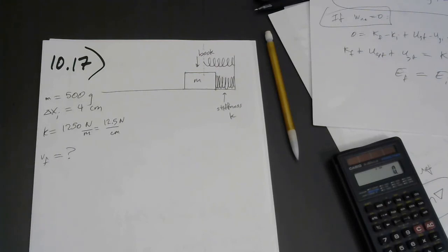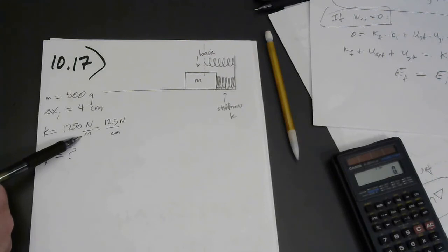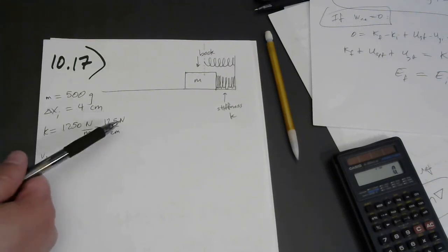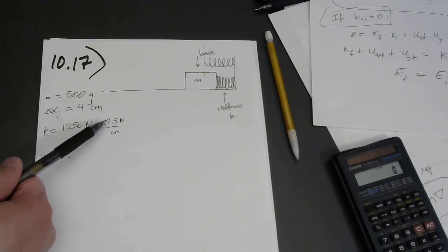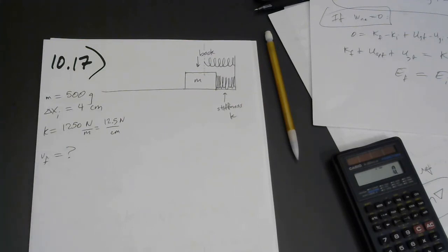But that's a little hard to interpret because, first of all, most springs cannot actually be stretched by 1 meter. They would break. And it's also just a big number. So remember that 1 meter is 100 centimeters. So take the decimal point 2 to the left. You could also say it takes 12.5 newtons or 3 pounds just to stretch it 1 centimeter. And that's a little easier to conceptualize.